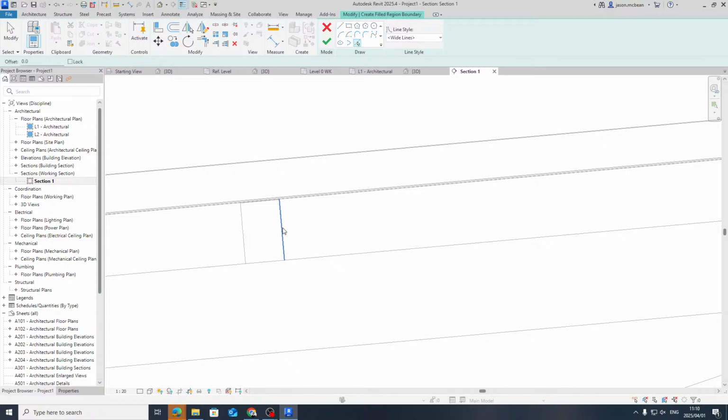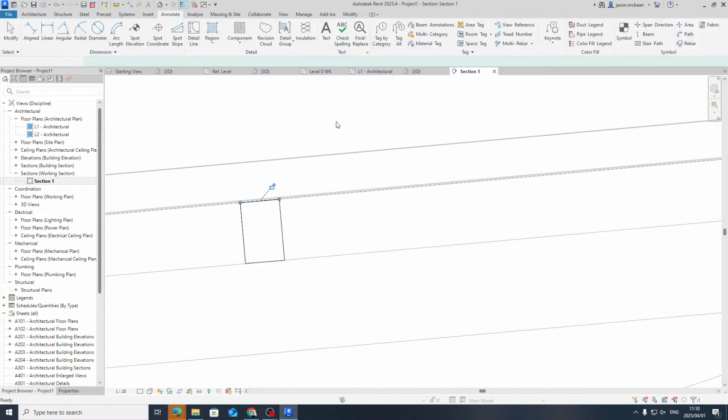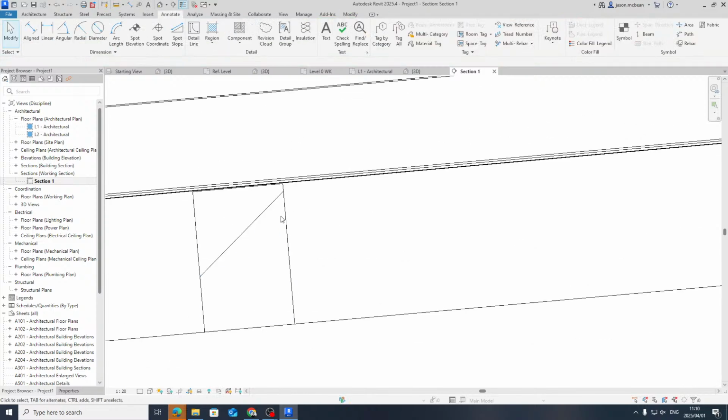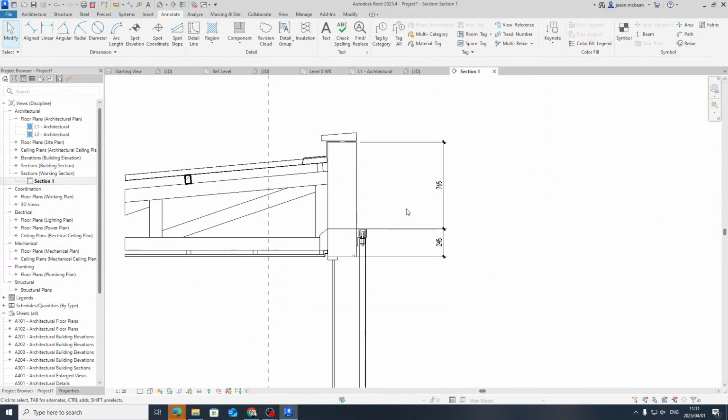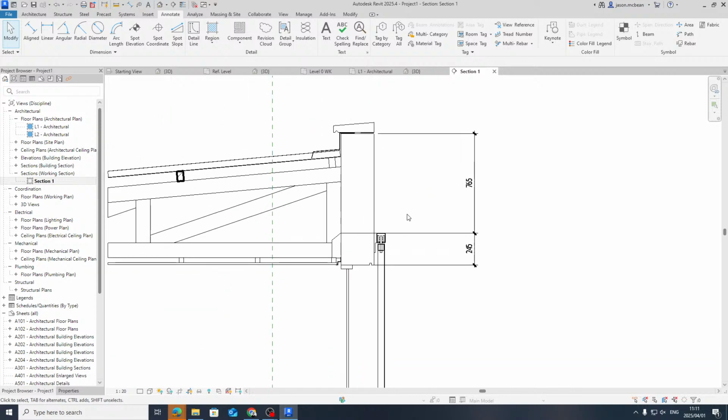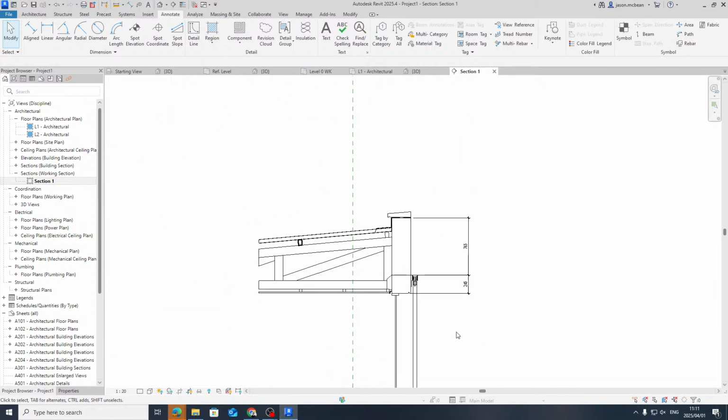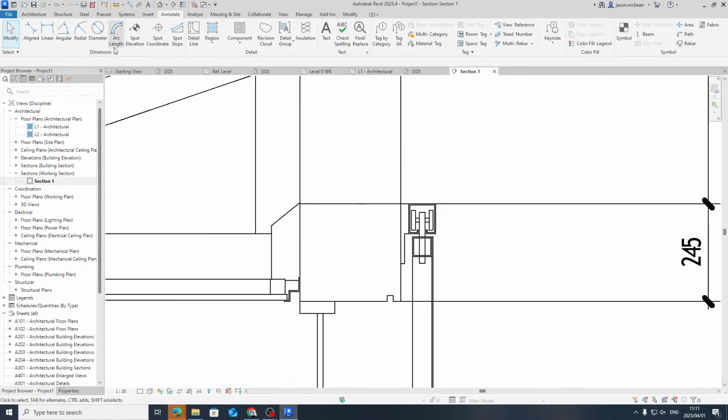Revit's very intuitive as well. It will select boundaries. So now I can start using all types of fills. So maybe this needs to be like a timber line. We'll switch on line weights because I want to start seeing the line weights. Now we draft over this. You guys need to understand Revit is a combination of 3D modeling and drafting. So that's why I wanted to show you this workflow.